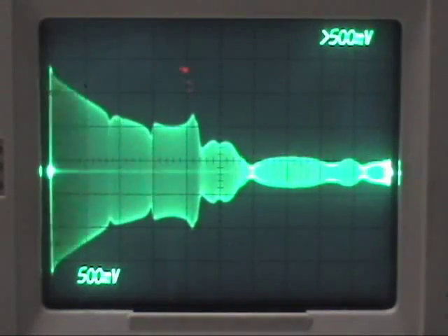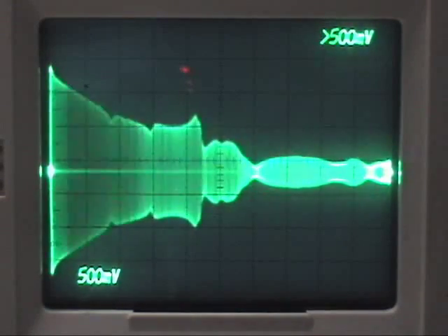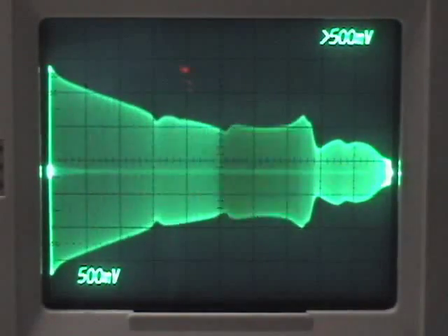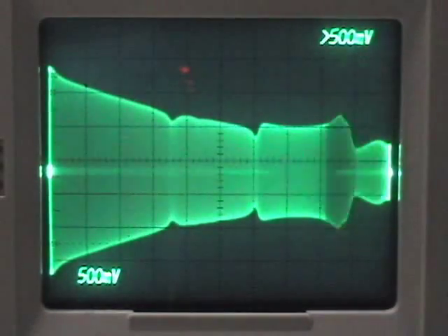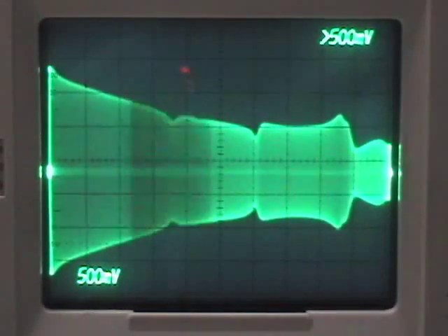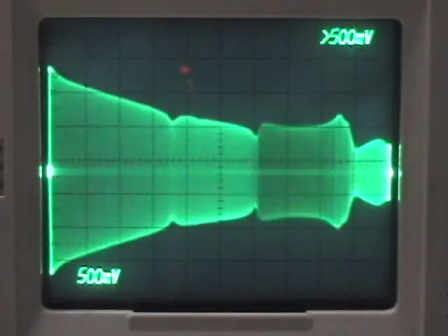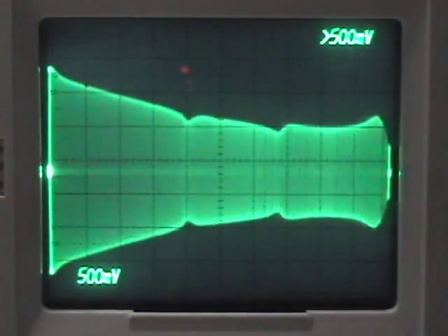You probably won't be using this amplifier up around 100 megahertz, so we can decrease the upper frequency response and take it down to 50 megahertz, and it looks a lot nicer. So that's between about 0 and 50 megahertz there. This amplifier would be real usable on any of the HF bands.